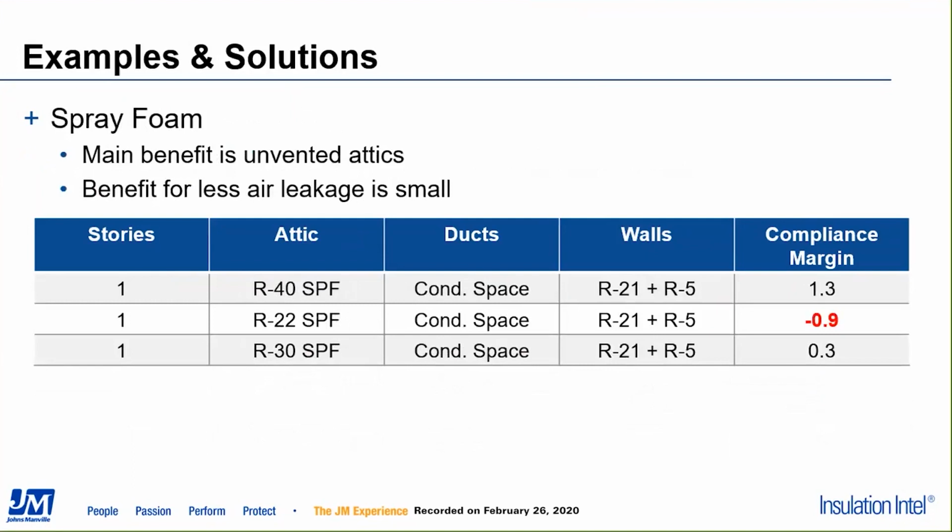Another question that does come up is, what about if I want to do spray foam? What sort of benefits do I get? The main benefit that we tend to get from spray foam is an unvented attic. So this very first row is that baseline example again, where we've got R40 spray foam. The ducts are now considered to be in conditioned space, so our compliance margin is good.